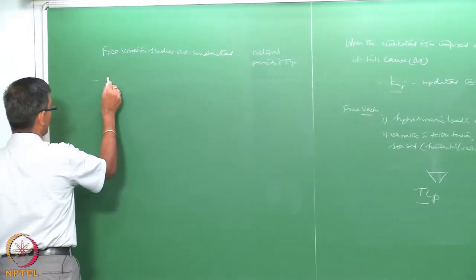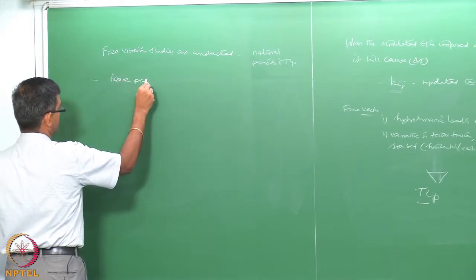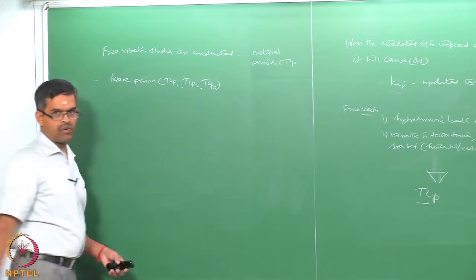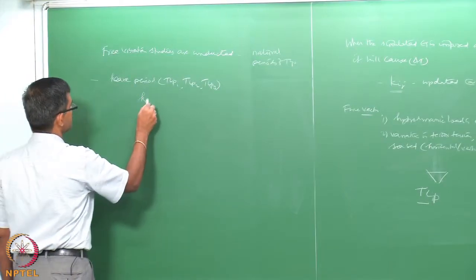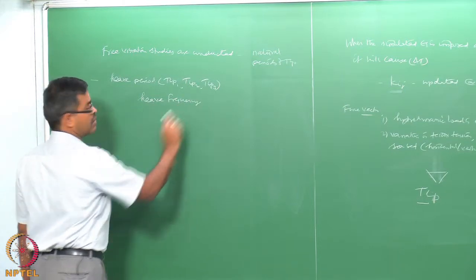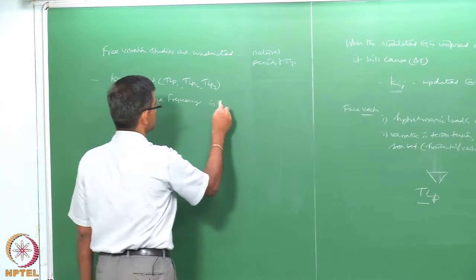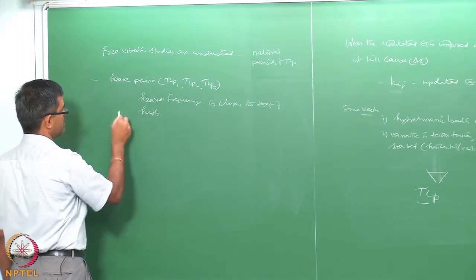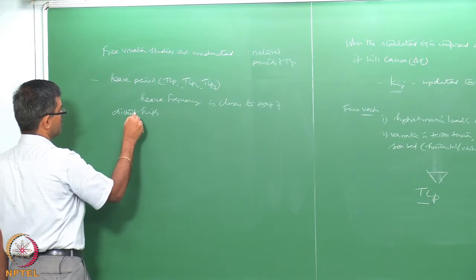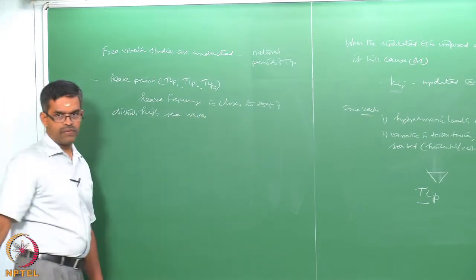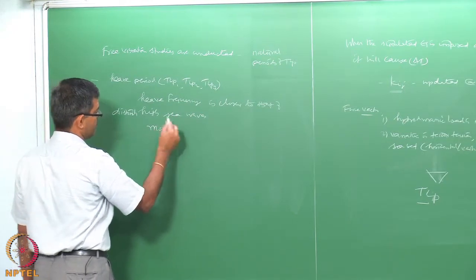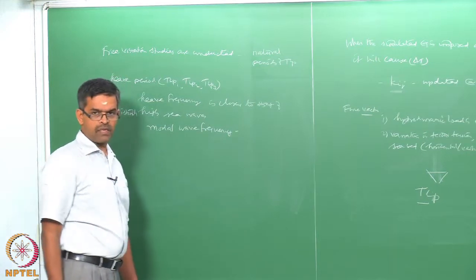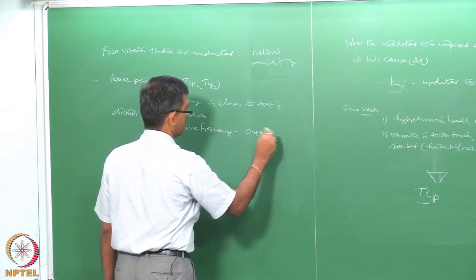So, interestingly, if you look at the values for the heave period of all the TLPs, the heave frequency is closer to that of the distinctly high sea waves, because we know the modal frequency used in the PM spectrum is 0.46 hertz, okay, used in the study.